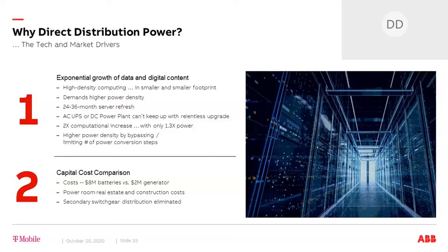This example has maximum limits of 600 kW per single row and 600 kW per single cabinet, with adjacent rows and cabinets still allowed. We can support 5,000 kW IT load over about 500 cabinets in Data Hall 1 to average 10 kW per cabinet in that room, but Data Hall 2 will be much more dense.